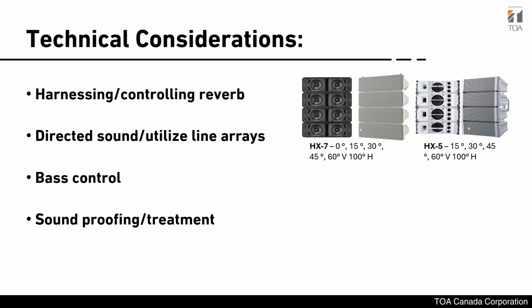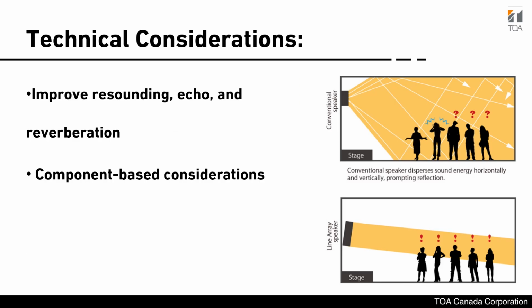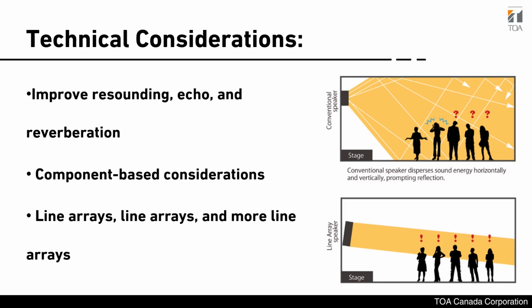When choosing speakers, it's important to control sound dispersion to avoid unwanted reflections. Walls, ceilings, and floors can reflect sound, especially with non-directional speakers. Minimize reflections early with sound-absorbing materials in walls and ceilings.